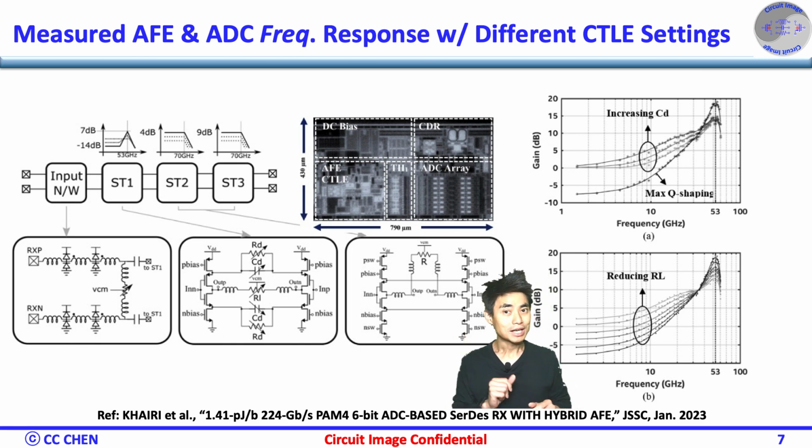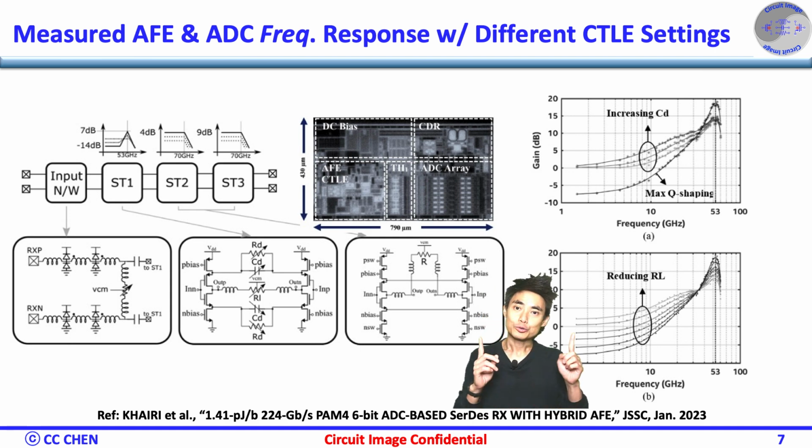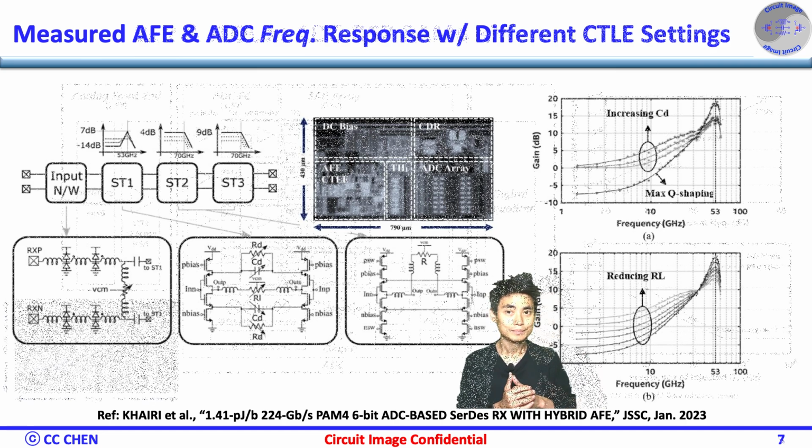In addition, there are 2 stages of wideband VGA after the 1 stage CTLE that can support a raw DC gain to better meet linearity requirements at the ADC input. Then the peaking gain between the 56 GHz and DC could be further increased and equivalently reduce the ADC input dynamic range. Let's look at more measurement data from their result.